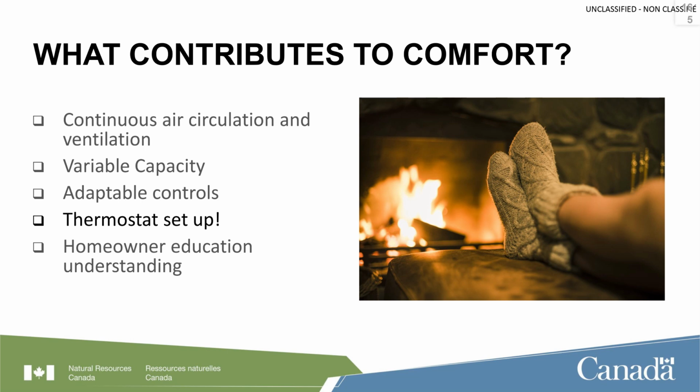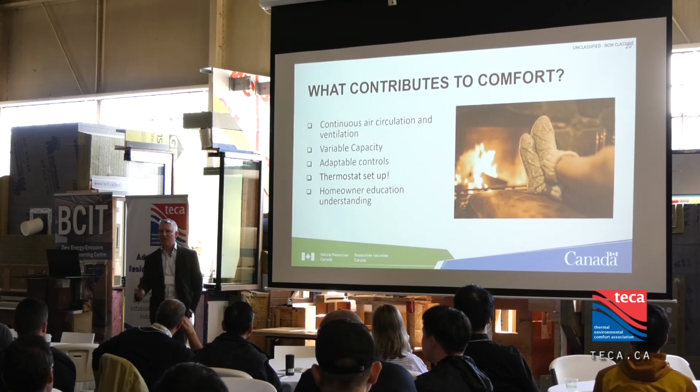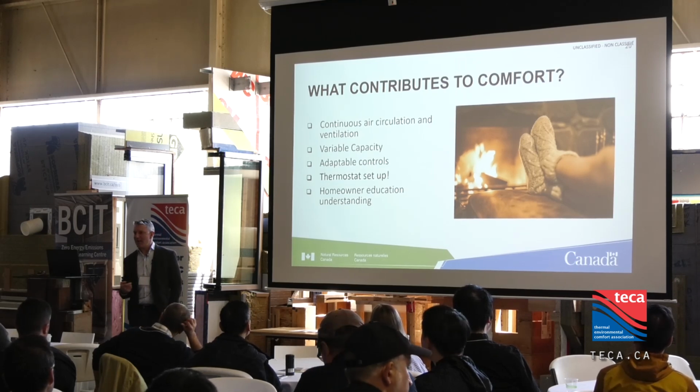It's almost mind-boggling, but I've always found there's a huge potential, even for some new home construction, the builders will take their new homeowners through the house and show them everything and how everything works. The homeowner might go, okay, that's fine and dandy, I'll forget this in 5 minutes, but at least that effort's been there. How to change filters, when to change filters, how to check them, what an HRV is and where the filters are.